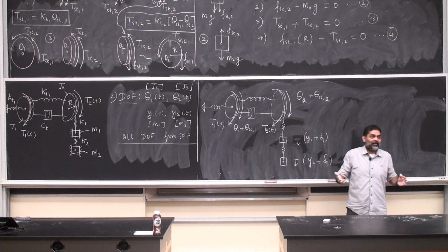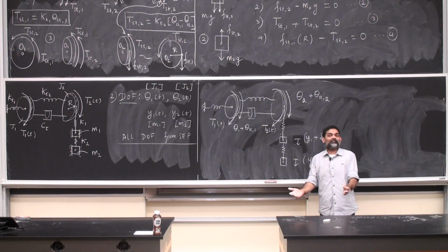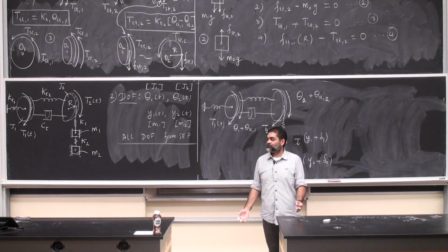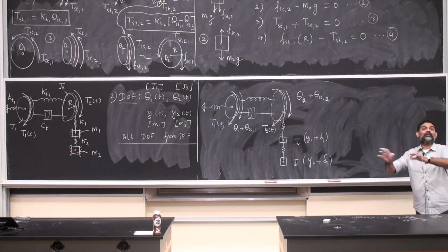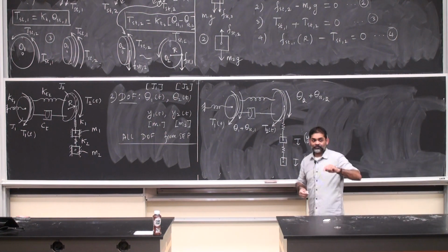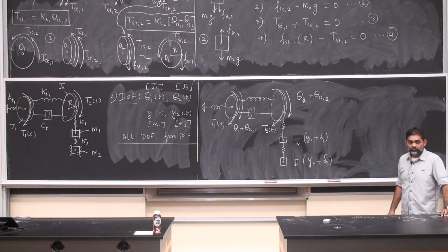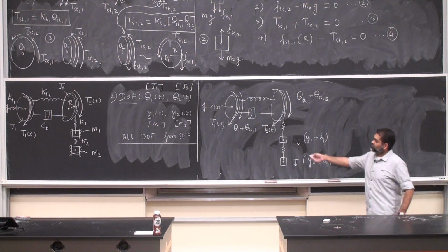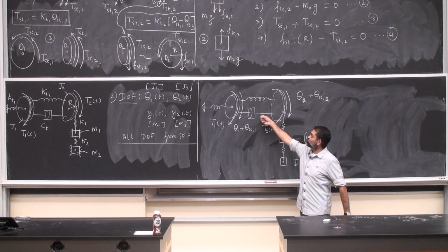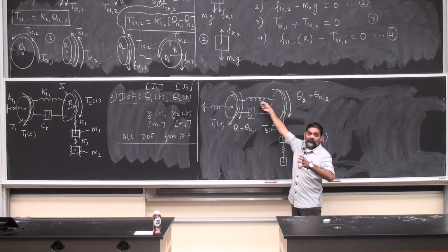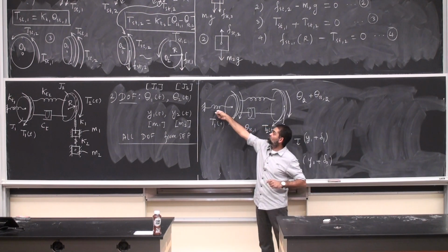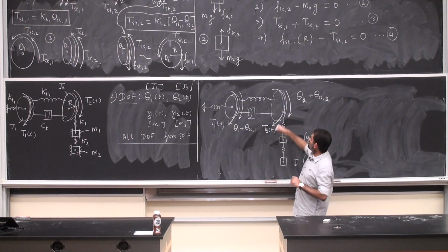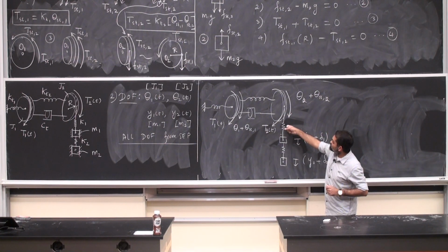To start off with, I have to have everything at rest. Everything has to be balanced at rest. If it is not at rest, then how am I going to do anything? Right? So you cannot have things in accelerated motion to begin with right away. Static starts first. Yes, question? So then, for any damping element, can you not have it by itself at all? You can have something like this, because in static equilibrium, this spring carries the burden of maintaining static equilibrium. But if I got rid of this spring and I put a damper here, but I still kept this spring, would it work? It would not work, because I would not have any restoring torque to the force of the spring here from static equilibrium.